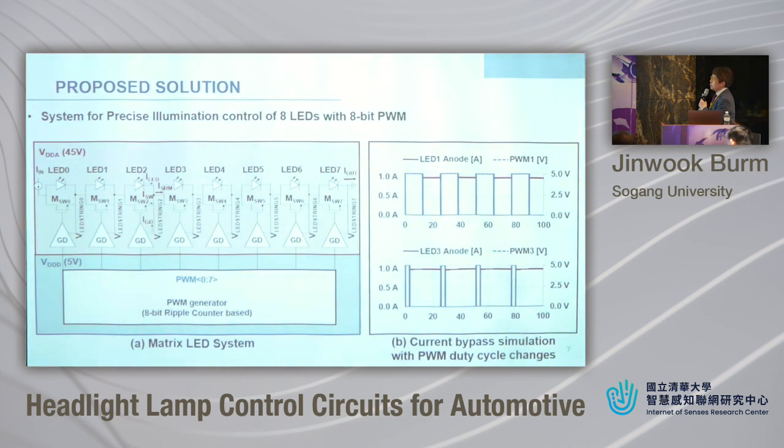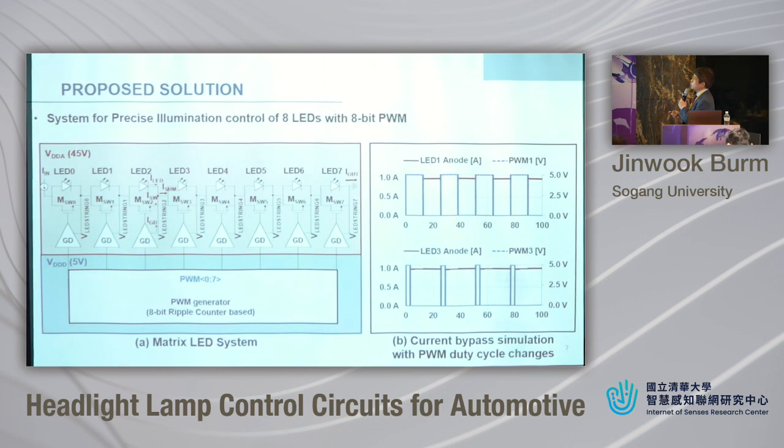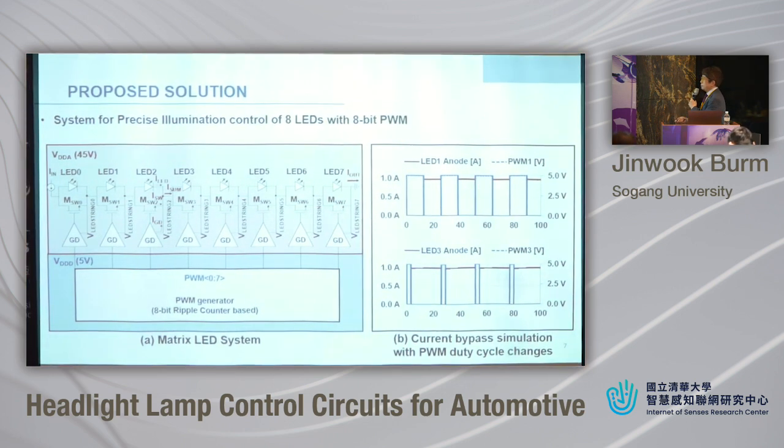So for this gate driver, the PWM control signal is here. Once this signal is high, this transistor is on, and in that case the LED is off. So this is showing the complementary on and off characteristics of the LED and the transistor. When the PWM signal is off, then the LED will be on.